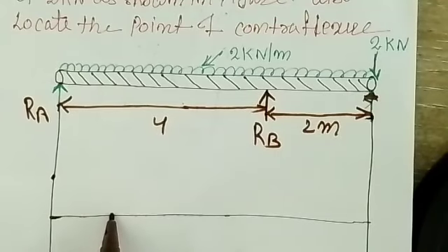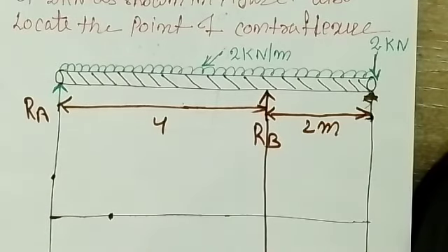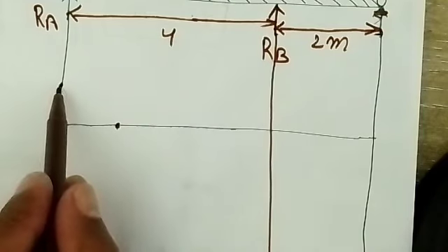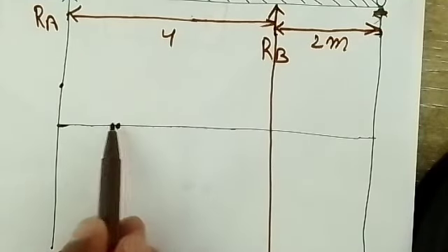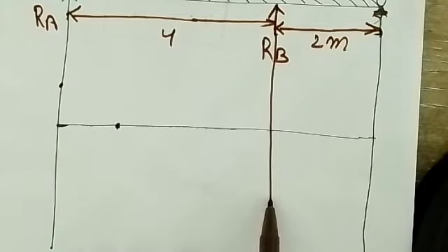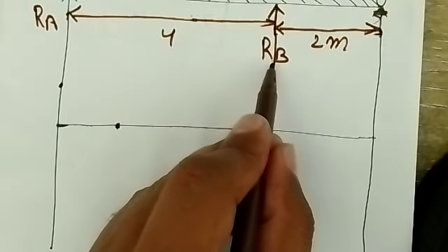And shear force becomes 0 at 1 meter here, let's say this is 1 meter, right? And this is the load that is given. Shear force at A is 2, shear force at 1 meter becomes 0, and shear force at B is minus 6 kilonewton, right? And then again at B, between B to C, the shear force becomes positive.